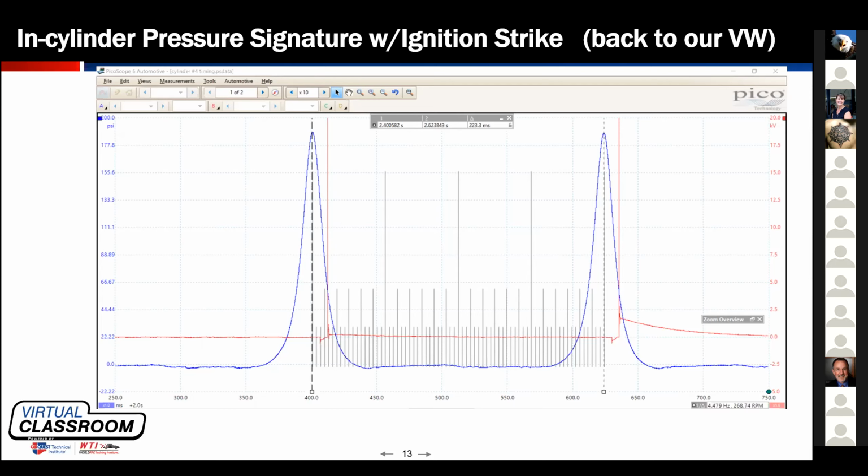And remember that my live data, the data I took off this Volkswagen, said the ignition timing was 6.8 degrees before top dead center. Now, not understanding anything else about an in-cylinder compression waveform, this point right here, what most of us refer to as point A, is the highest peak pressure found in that cylinder.